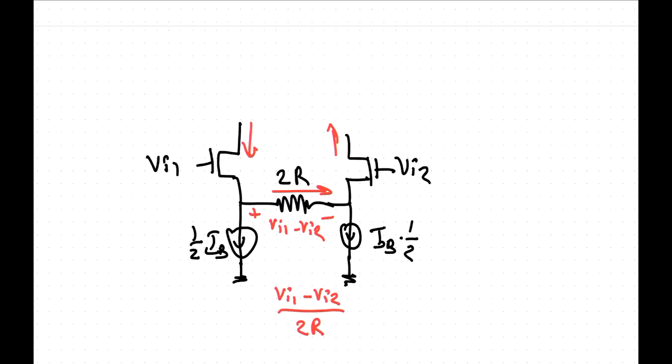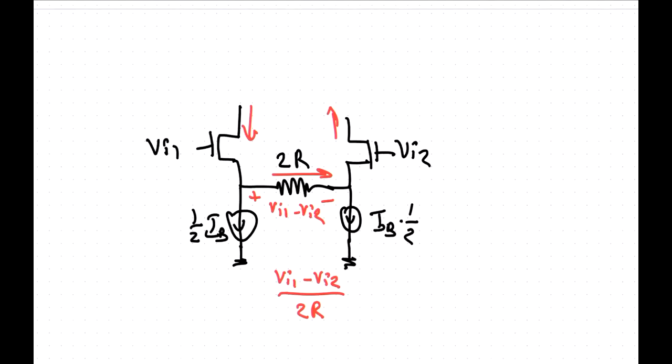So typically we wrap that core transconductor into a couple of current mirrors, probably with cascodes at the output, so we have a high output impedance. So that will look maybe like that.